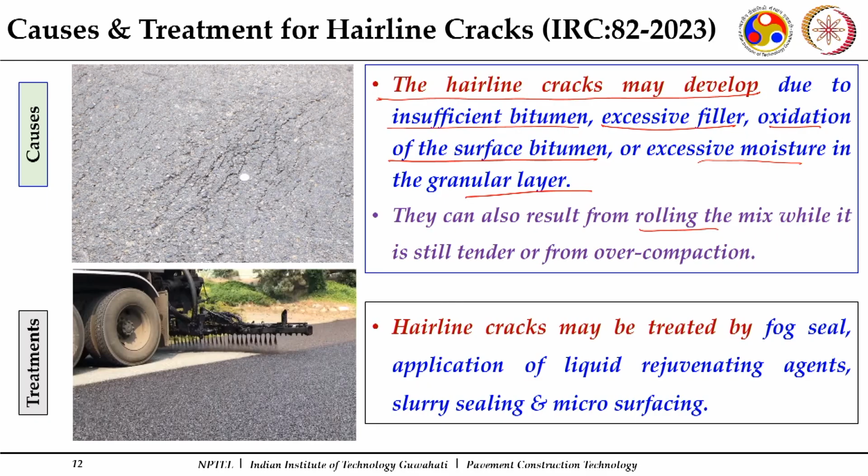Then you start with your rolling operations. When you start rolling, the mix should be in such a condition that it can be compacted, otherwise it will start flowing in front of the rollers. That is the case with tender mixes, or even when you go for over compaction; in those cases also, fine cracks develop in your surface.